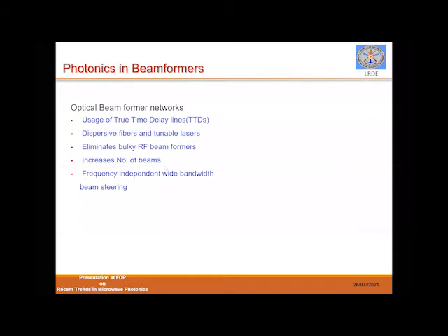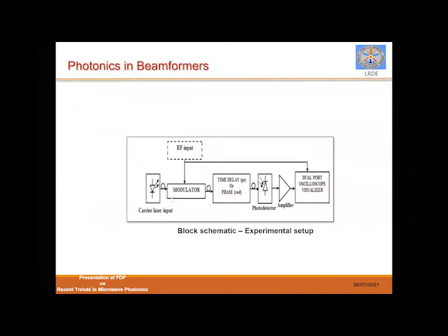So you will agree with me that where we are dealing with very big systems, we can minimize the total size of the chip with the help of photonic integrated ICs. Now, frequency independent wide bandwidth, I explained to you: because of the wide bandwidth capability of photonics, the same chip can be used for your input S band signal, S for ship, and even up to L, C, X, all are RF band I am talking about. And frequency independent wide band steering is possible.